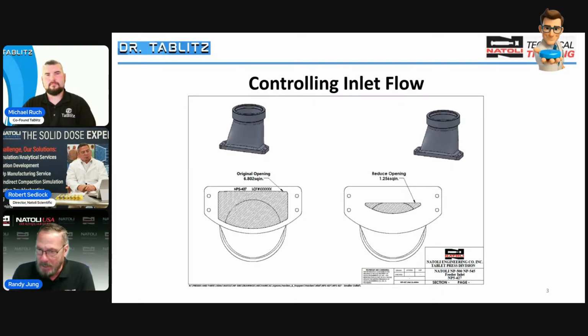You get the raw speed, so maybe it helps spill the dye, maybe it doesn't. But faster speed gives you more torque. If I have a lot of powder in the feeder, sometimes people speed it up to get that torque. They don't really need the speed, but they need the torque. And then that's how they end up over mixing and getting segregation.